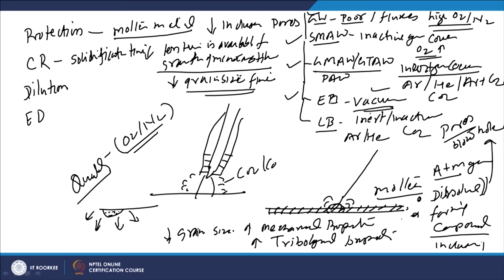So, it is important to see how the change in welding processes, and change in the conditions which are being used for depositing the bead on plate, will affect the cooling rate, which in turn will affect the solidification time experienced by the molten metal during the bead-on-plate deposition, and that in turn will affect the microstructure as well as the mechanical properties.